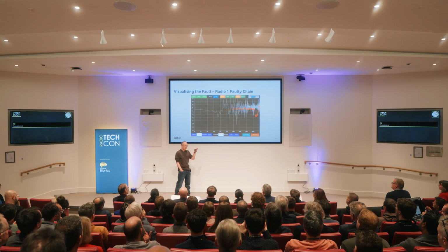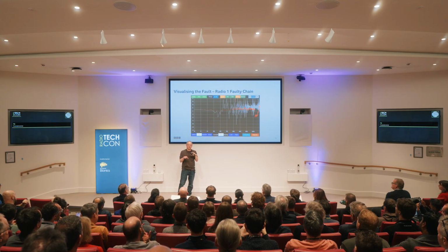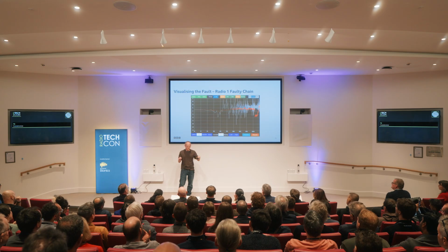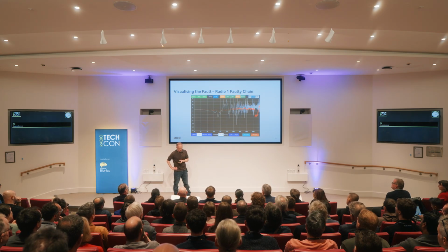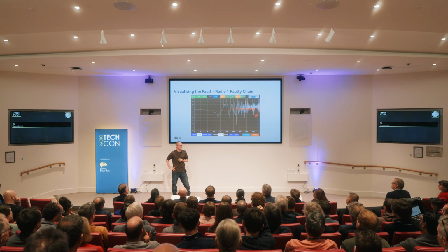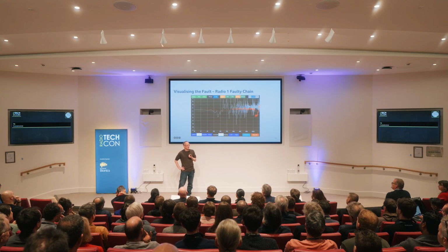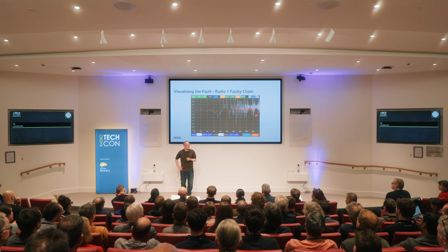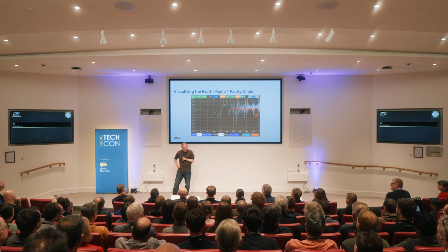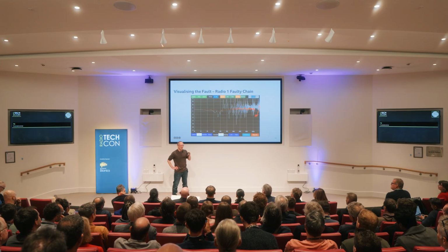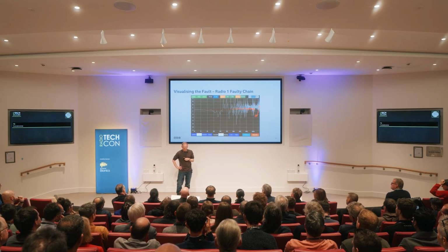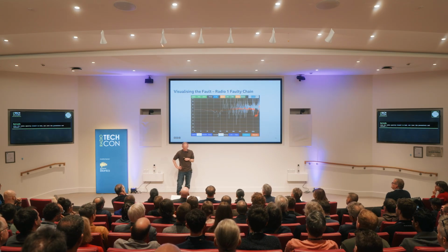Which, as you could see, wasn't as flat anymore. It's all over the place, and also, that previous one, the red line stayed pretty still. The average was there. On this, the rolling average is constantly changing. And this is a pretend faulty one. I couldn't find any, at the time, bad recordings of Radio 1 going to air, which was quite good, really. So I took a good one, and I basically stuck in some hard clipping at negative 6 dB.